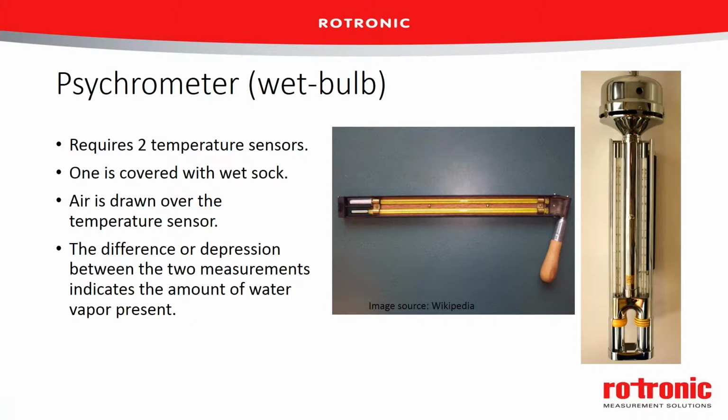So the psychrometer is a device. We don't see them around too much anymore, but they used to be very common. A manual sling psychrometer, as is shown in the center picture here. All a psychrometer is essentially is two thermometers. So we're not measuring relative humidity directly, we're measuring temperature two times. The bottom thermometer in this picture is what's called our dry bulb thermometer. And this is just measuring the ambient temperature in the environment. So just the temperature that we normally see.